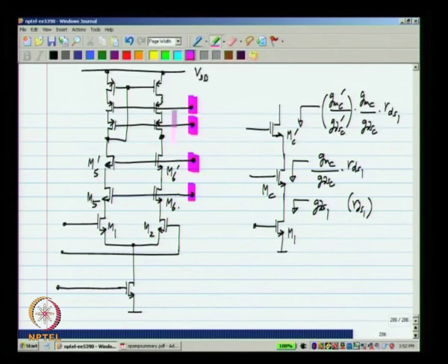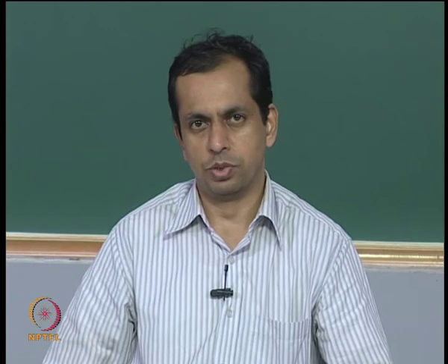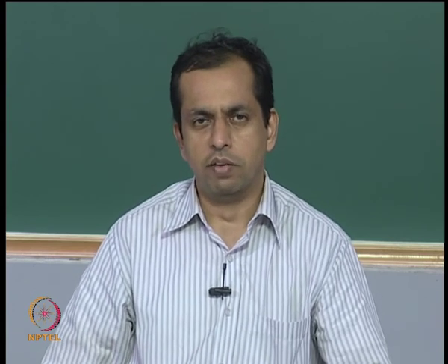of course, a similar thing can be done with the folded cascode as well. Also, an additional constraint is that you have now stacked more transistors. So, that means that things will be constrained even more than before. Okay. So, you can have more and more cascodes, but you will have lesser and lesser swings, but when you have a two stage op amp, the swing at the output of the first stage does not have to be very high. So, it is possible to do this.